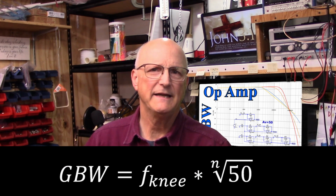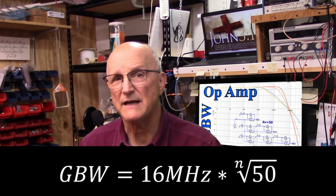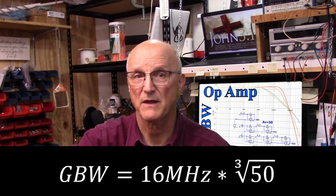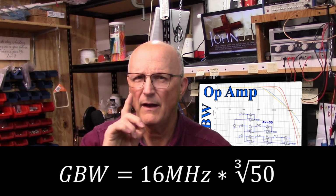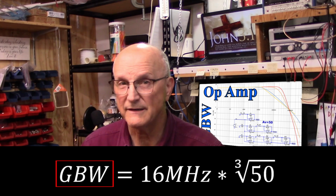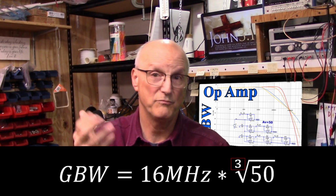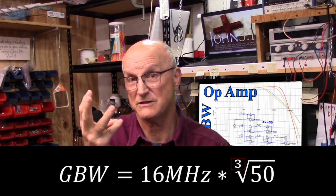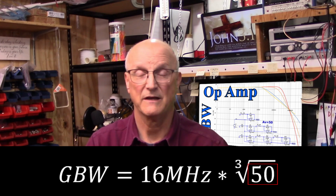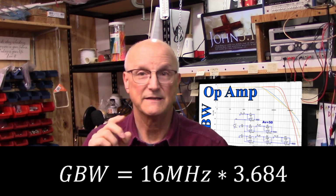For example, suppose that I need an overall gain of 50. Furthermore, I need that gain up to a frequency of 16 megahertz. To do this, I plan on distributing this gain across 3 identical amplification stages. So, what is the minimum needed gain bandwidth product for my op-amp? Well, gain bandwidth product is equal to 16 megahertz times the cube root, cube because I'm using 3 stages, of the desired overall gain, which is 50. So that gives me 16 megahertz times 3.684 is equal to 58.94 megahertz.